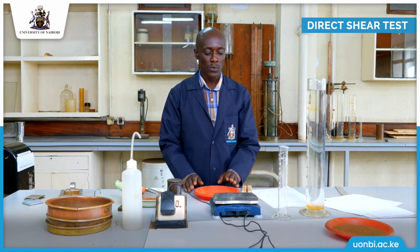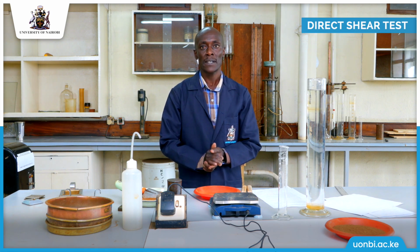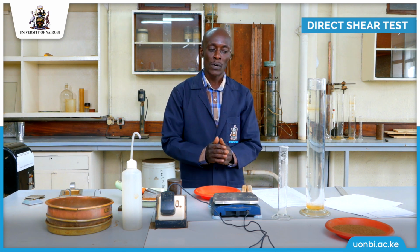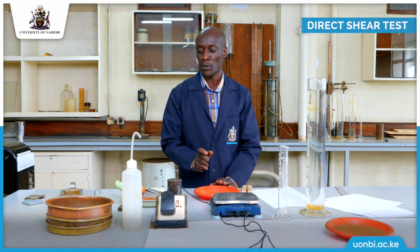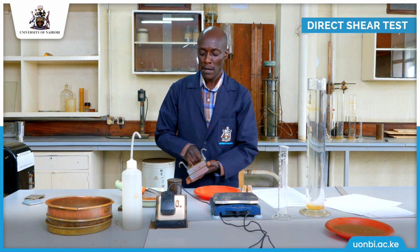Before you do this test, you need to first of all have done what we call the compaction so that you are able to get the MDD, or the maximum dry density of the soil, and also the optimum moisture content of that soil sample. Those are the initial steps that you need to have done, because the MDD and the OMC are what will enable you to calculate the amount of soil sample required to fill this standard mold that we use for shear test.